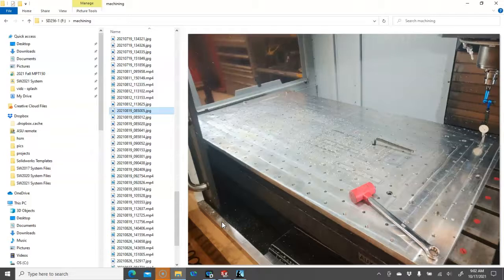So part of the subplate and tooling plate geometry is to get this flat and allow that if we overcut anywhere from 2 to say 5 thousandths, sometimes a little deeper, into the plate, it's a sacrificial plate. It pays for itself to go through this process by having a clamping surface that is able to be flattened and to make the setups a lot easier.